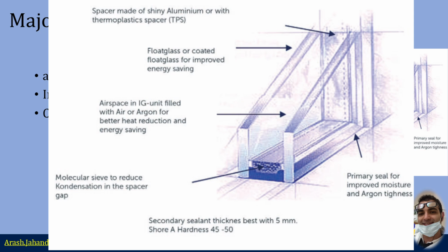The secondary seal must be robust enough to keep the glass panes properly spaced and bonded, yet elastic enough to accommodate thermal and mechanical stress over time. What's more, in the event of minor leaks in the primary seal, the polysulfide-based secondary seal provides a reliable backup, helping to extend the service life of the entire unit.